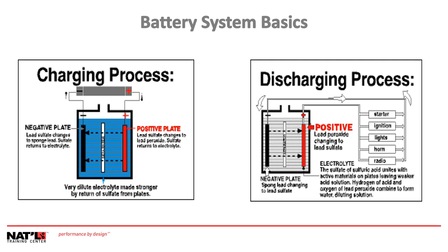Now let me expound a little on this 2 volts per cell. That's typical of a lead-acid battery. Other types of batteries have different cell voltages. They're all going to be somewhere in the neighborhood of 1 to 2 volts, 2.5 volts per cell. Most people don't realize that a lead-acid battery operates in a constant process of charge and discharge. When a battery is connected to a load that needs electricity, such as a starter in your car, current flows from the battery and it begins to discharge.